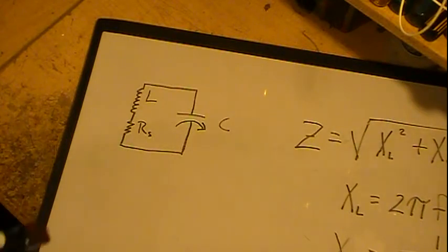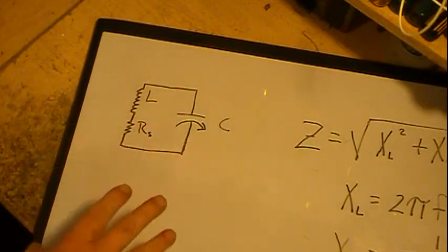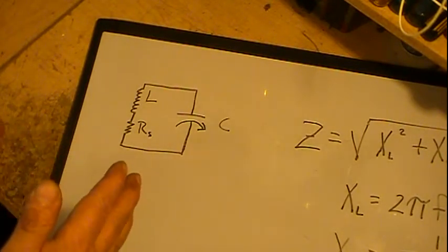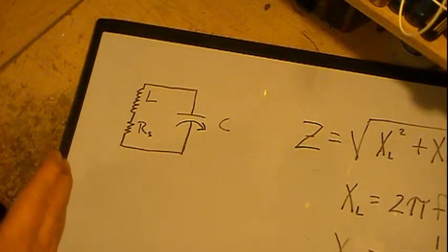And so if you go rewinding one, it may be a little different, slight differences in inductance, but more importantly, a difference in resistance. Now, why is that important or not important? And I'm here to tell you it's not important what the resistance is, at least as far as the tank circuit is concerned, as far as the resonant frequency. That series resistance in that coil matters none as far as the resonant frequency in the tank circuit.